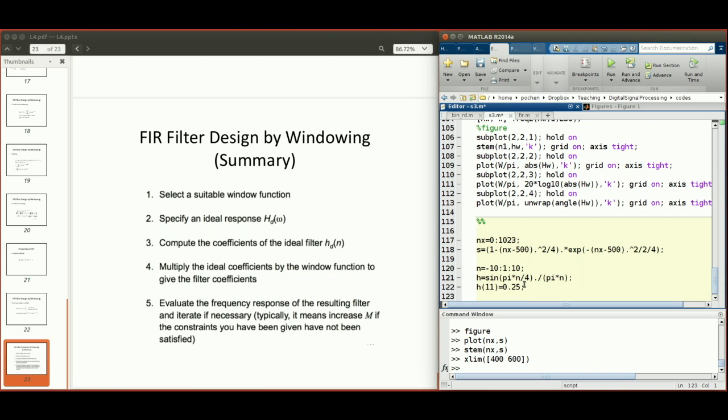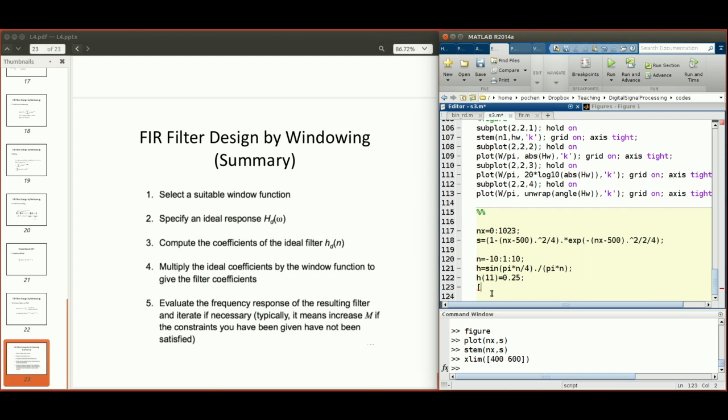And then what we can do is to apply this filter onto the input signal, right? How do we actually apply the filter? We can apply the filter by using a convolution operation, right? Because both the input signal and the filter have been specified in the time domain. So if you wanna apply a filter to an input signal, you can do it either in frequency domain or in time domain, right? In frequency domain, it's just a multiplication, and we know from the Fourier properties, multiplication in the frequency domain is actually equivalent to convolution in the time domain.